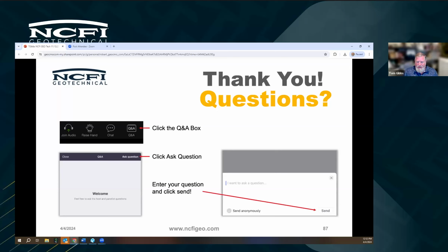So the answer really to that is no. Single component equipment, though, is very inexpensive. The Terrapin cart is not necessarily mandatory to do what we do. Basically, a 1 gallon per minute airless paint pump is the primary tool that one would use to get into doing single component equipment or grouting. And so you don't really need to spend a ton of money to do that.